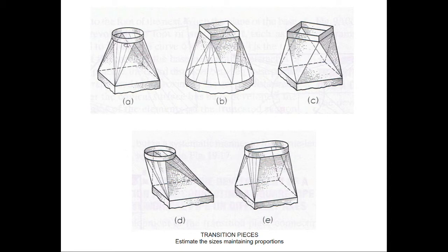What we're going to need to do is do a 2-station loft between these two and use what are called guide curves to force the shape to represent what we see here. Then we can come back and either extrude, or we could loft or push-pull the opposite ends to make up these transition flanges.